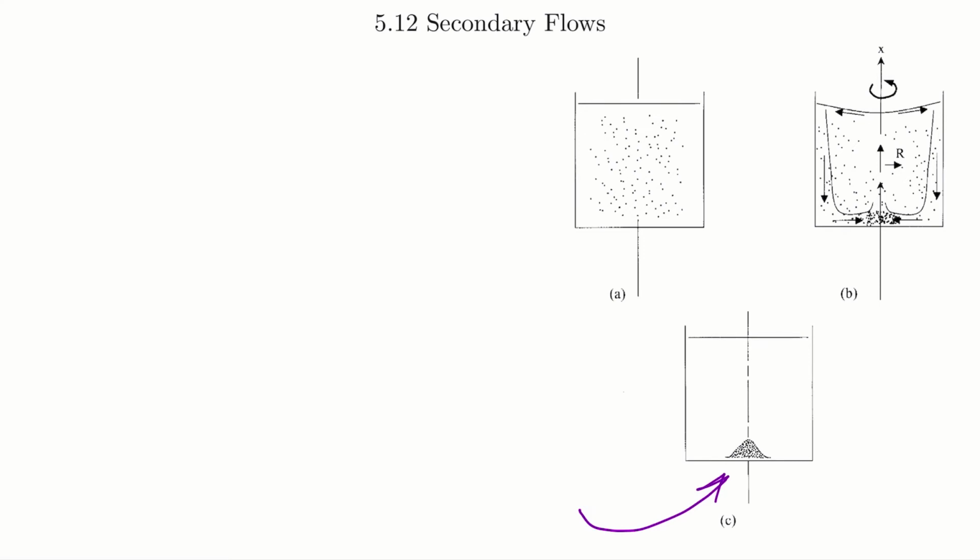Okay, so what happens is when we're stirring, we're imparting this velocity in the u theta direction. So we have this u theta as a function of r as we spin it, and that's large enough for the Reynolds number to be big enough that the boundary layers on the sidewalls and the bottom are really thin. And then if we look at our r momentum equation, the biggest terms in the r momentum equation are these ones here.